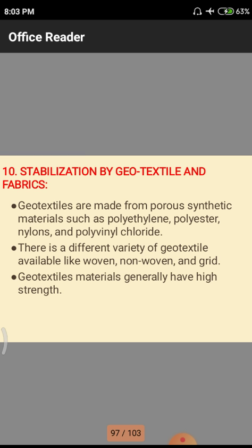Why? Because this polyvinyl chloride will not react with the water, so there will be no bond breaking. If we simply use steel pipes or alloy pipes or iron pipes, automatically water will react with the iron and it will form Fe(OH)2. That means iron hydroxide, so it will break the total structure. After 5 to 10 years, we go for refitting the pipes and plumbing work.